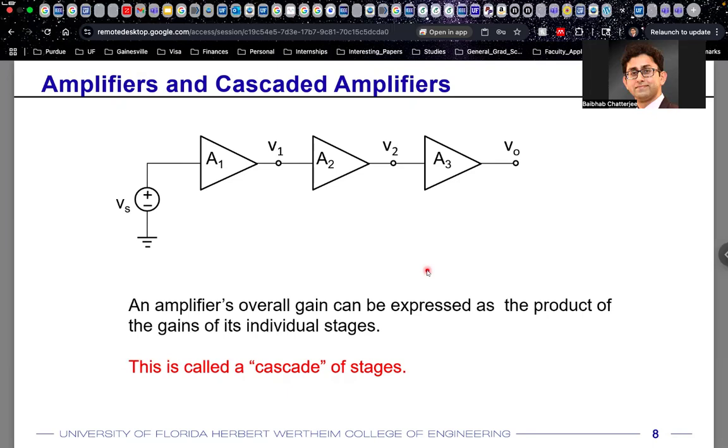But the output voltage, as you see, is saturating. The output is not becoming 0. And the meaning of output saturating is that the output is getting flipped and it's not increasing anymore. If it had increased infinitely, then you would see this curve just goes on and on. But it does not increase infinitely, it gets flipped at this position. And as you increase your input voltage even more, it will stay here. It will not increase at all, it will also not decrease.